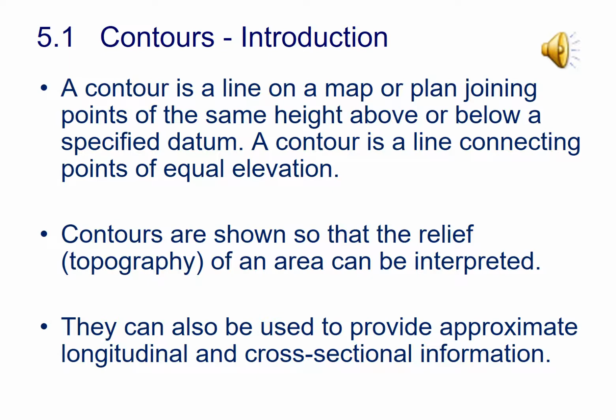So contours are shown so that the relief or the topography of an area can be interpreted. It shows where the hills and the valleys are. They can also be used to provide longitudinal and cross-sectional information, and that's really important if you're working on a scheme where you're either excavating or building an embankment. You need to know how much soil you need to import to the site or how much soil that you're going to have once you dig a trench.